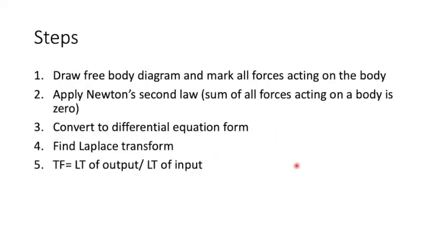So what are the steps? The first step is to draw the free body diagram of the masses M1 and M2 and mark all the forces acting on the body. The second step is to apply Newton's second law. The third step is to convert the force balance equation to the differential equation form. Then we find the Laplace transform of this differential equation form. And finally, we find the transfer function as the Laplace transform of output divided by the Laplace transform of input.